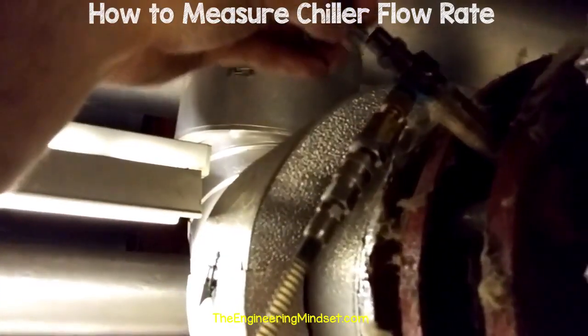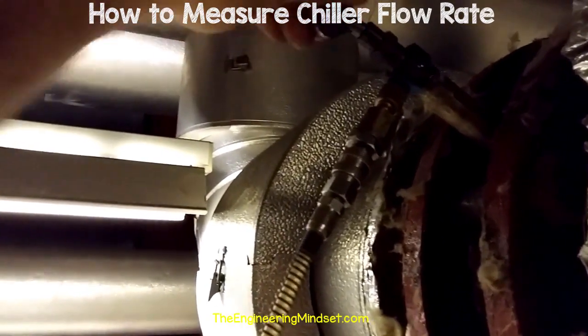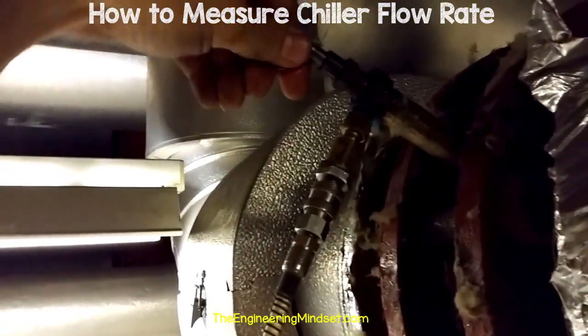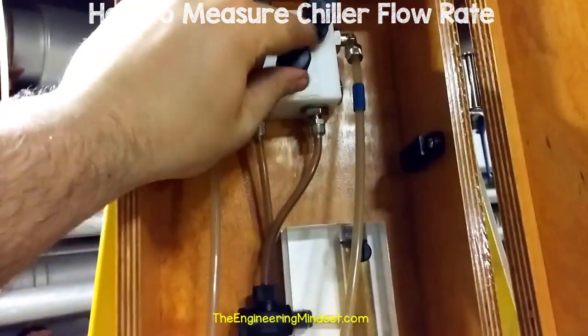Now once you're happy with the 0 alignment, you can then open up the low pressure side of the orifice plate. Sometimes when you open these valves up, they dribble just a little bit. If this happens, then just make the connection a little bit tighter and it will stop. After that, you can then open up the low pressure valve within the manometer. And once that's fully open, you can then begin to close the bypass valve.